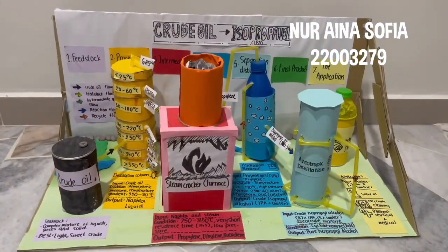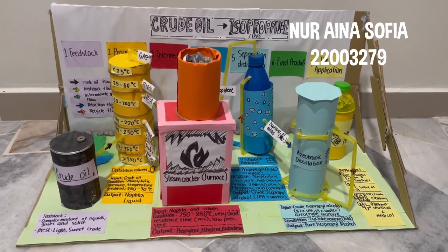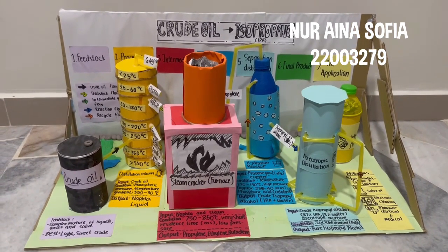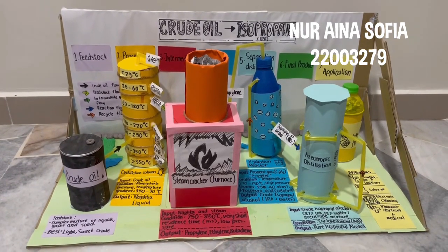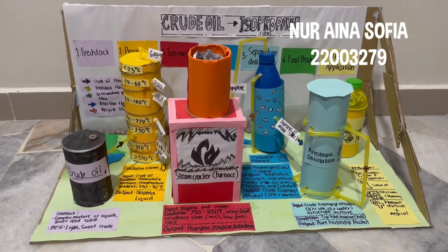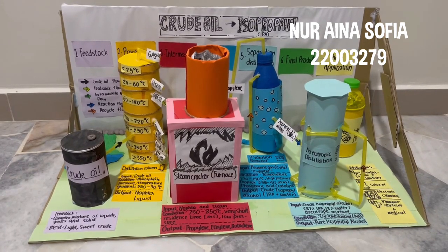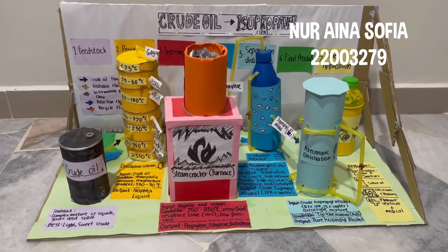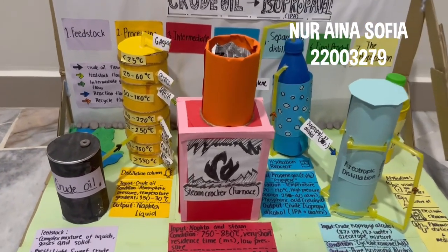The process starts in the convection zone, where naphtha at 50 degrees Celsius and 5.8 bar is mixed with steam to reduce coke formation and heated to 616 degrees Celsius without cracking. Cracking occurs in the radiant zone at 600 to 900 using 80 burners, producing ethylene, propylene, butadiene, methane, and aromatics.